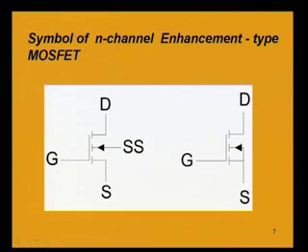Between drain and source, exactly as we have seen, there is no channel established. Only after we apply the gate to source voltage, then only we can establish a channel. So, that is significantly reflected by these broken lines, and this is the substrate terminal. This arrow mark is signifying the direction of current between P and N, because it is an N channel. In N channel, P is the substrate. So, the current is from P to N, that is the normal direction of current in a PN